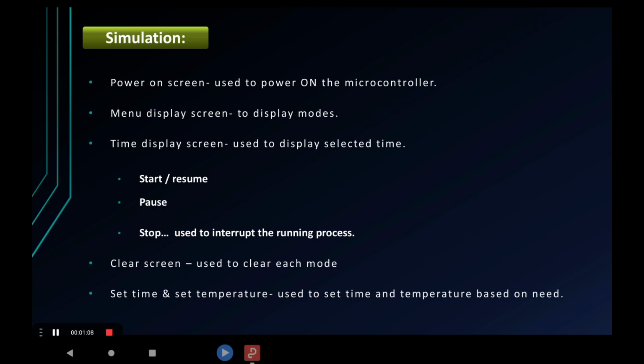Go to the project, next click on Create New. Next, Microchip Embedded, next, Standalone Project. Next, select family which includes mid-range 8-bit MCU. Next, select PIC16F877A. Then click on Finish. Select the compiler toolchain. This is the XC8 compiler. Then next, give a name for the project as microwave oven or anything you would like to. We select the project location and the folder, then finish.